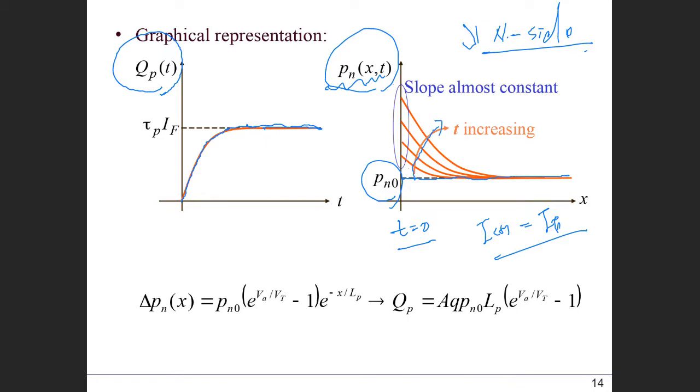Now, in here you have to understand one thing, which is the current in the structure. Okay. So if you remember, when you look at the PN junction diode, especially a P plus N diode, if you look at this hole current in the structure, in this neutral region we calculate it from the diffusion current in the neutral region.